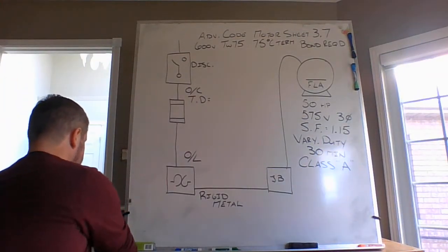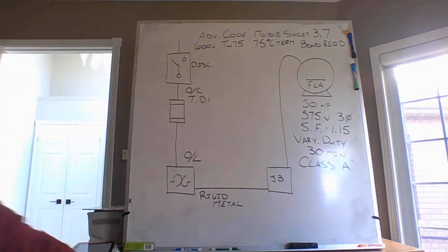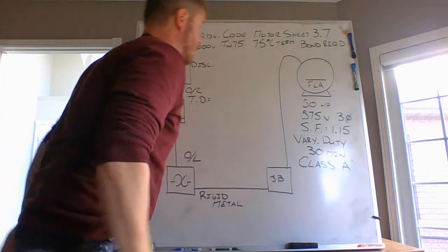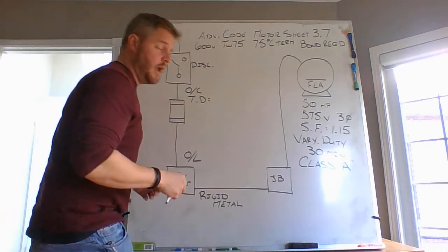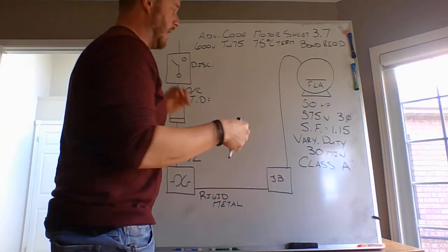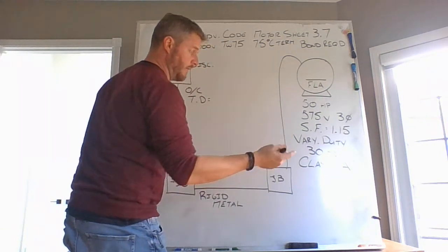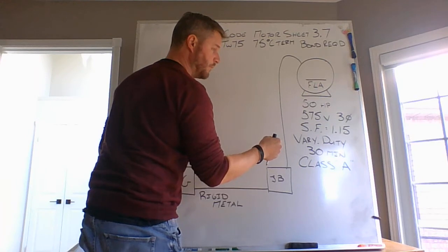Okay. Because you guys are very close to writing your CFQs, keep this in the back of your mind. When you're looking at 50 horsepower and essentially a 600 volt motor, keep this value in the back of your mind. When you hit a higher voltage like this at 575 volts, you're about 1 amp per horsepower.